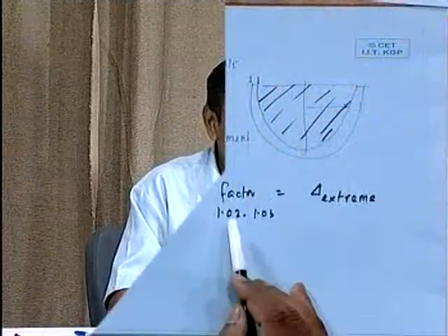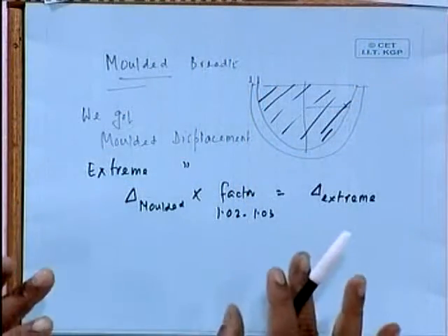But otherwise, what we have got is essentially 7 integrations that I showed earlier per water line. If you could do that, the entire hydrostatic calculation is available to you. And then from that it is one line. Somebody wants extreme displacement, you just multiply displacement with some factor. Somebody wants something else, which will be all a function of these numbers.